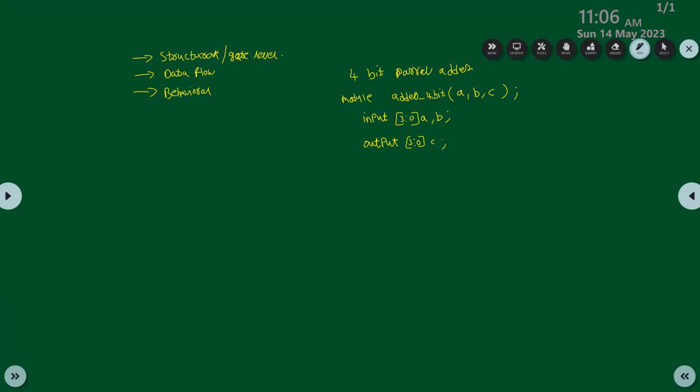Okay, so let's do it this way in module. Here I'll open another module. The name is full adder. Here also A, B, C. Full adder means how many inputs? 3 inputs and 1 output, Z. So remember, this is a full adder. It will require 3 inputs and it will give only 1 bit output. Here you can declare in the same way: input A, B, C, output